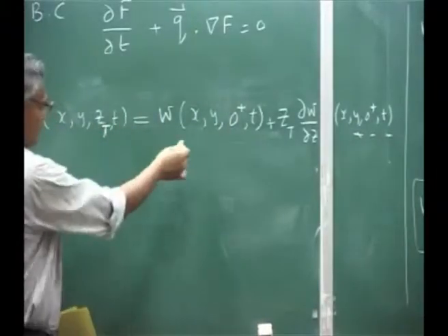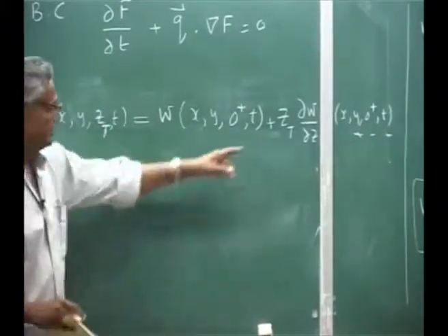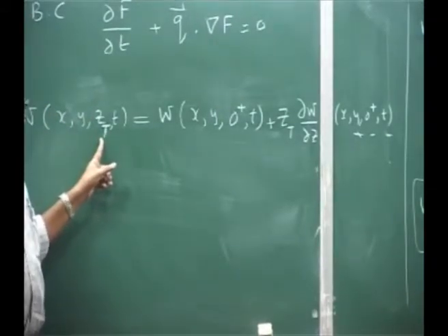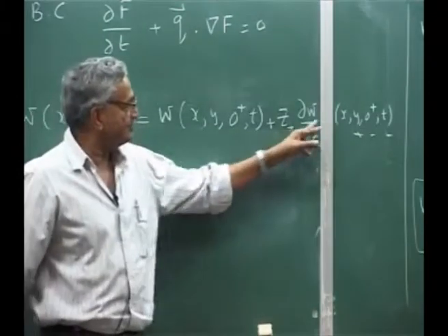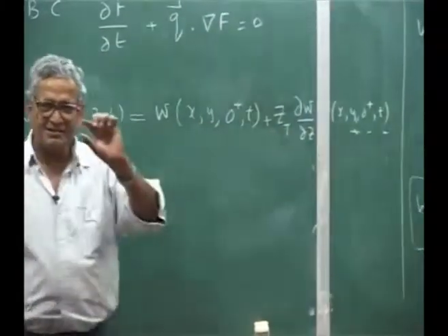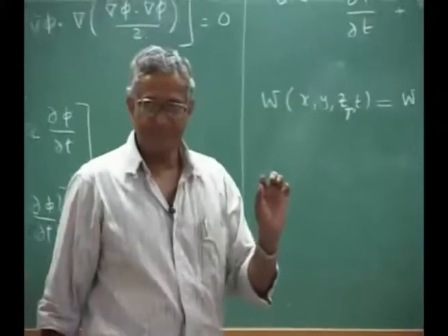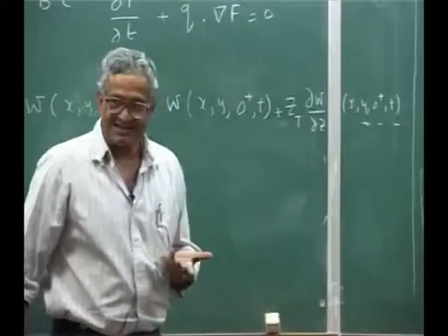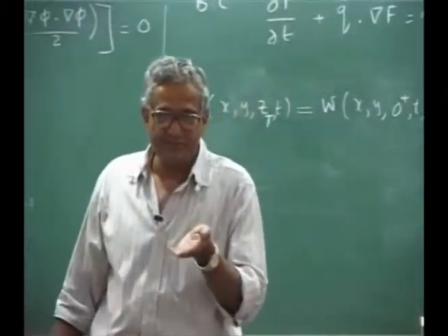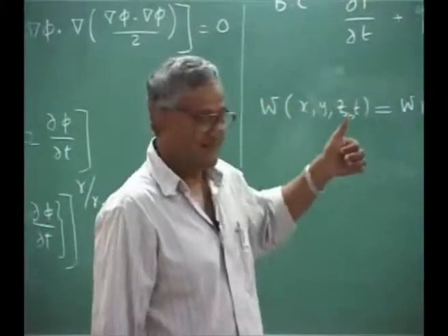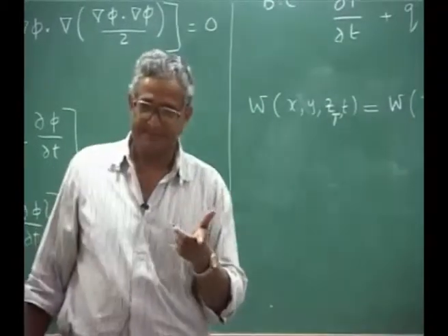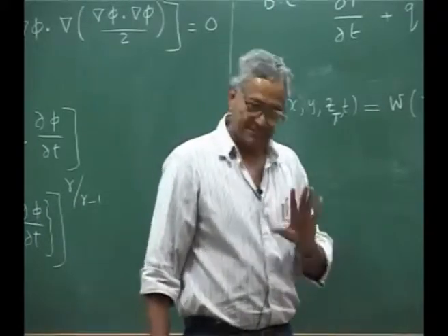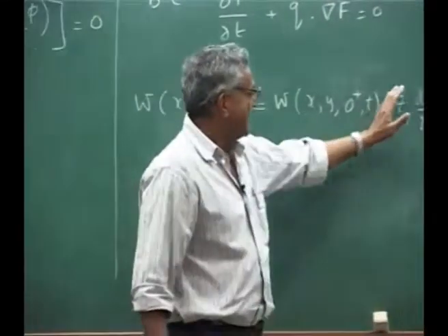Again, similarly for the bottom surface, you will put this is b, and you say that the thickness is not very large, and the slope delta W by delta z, that is the variation of the flow velocity with respect to z, is not very large. That is, there is no sharp gradient in any of these things. This is an assumption. Then you say, I neglect this term.